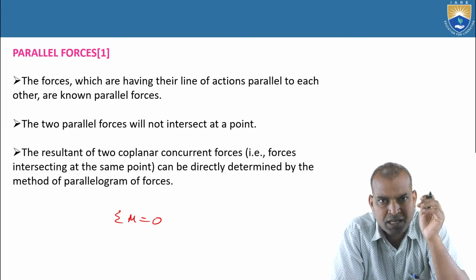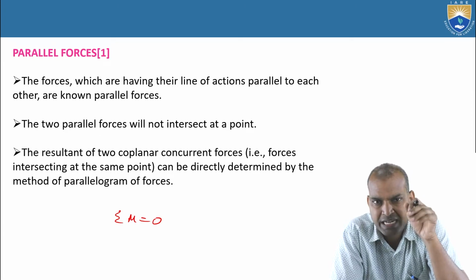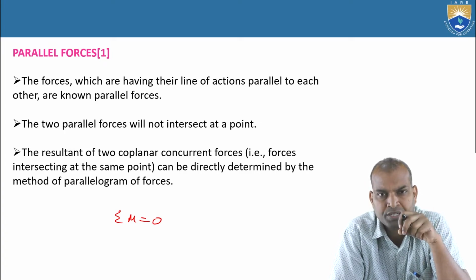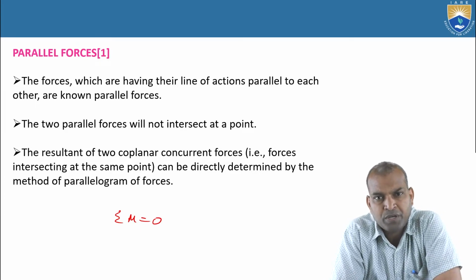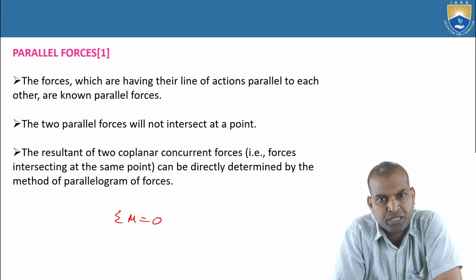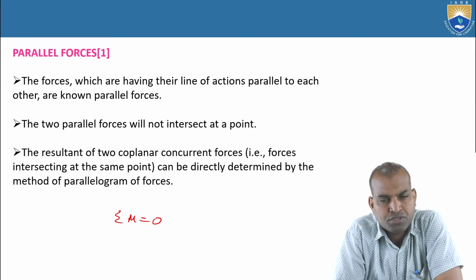The parallelogram law of forces can be applied when two forces are acting on a particle, and those two forces are concurrent at one point on your body. That means a coplanar concurrent force system. How many forces in the parallelogram law? Two forces have to act. Then we can find the resultant of these two forces by using the law of parallelogram of forces.